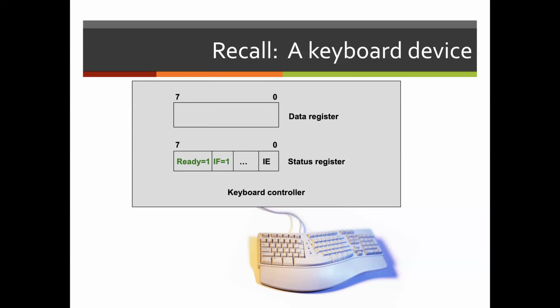And so if we were to represent this in our system, we will have our ready bit to represent the question of, is there a new character in the register? And then we'll also want to have our appropriate interrupt enabled as well. And that will just basically ask, is the processor allowing the device to execute?